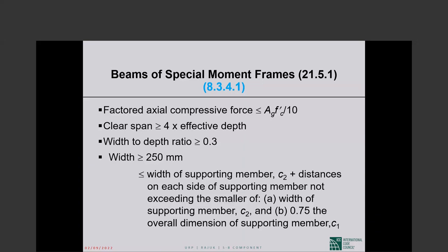I also mentioned they are used in conjunction with 100% lateral force resisting shear walls, or sometimes it could be steel brace frames. So it is not that flat plate column frames cannot be used in design category D buildings. I never said that. Nobody has ever said that.